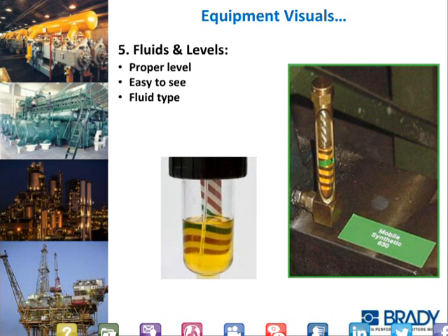And you can see from quite a distance away where the lines are magnified, and it's above that green line level. The other zebra card in the center has a green line printed onto the card, and that's a customized Brady label that you make to show what the level is. And they're actually stuck on the outside of the gauge. They're not in the fluid level. Makes it a lot easier to see. Again, we call those zebra cards.